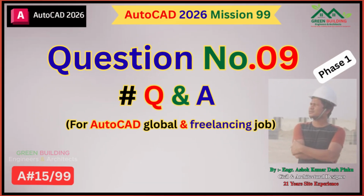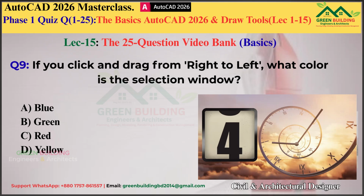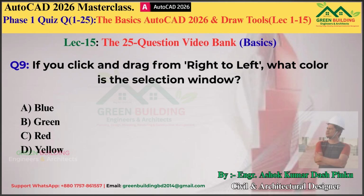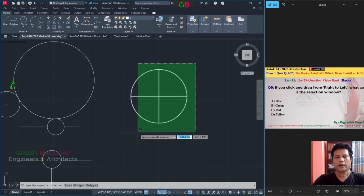Question number 9. If you click and drag from right to left, what color is the selection window? Option A for blue, option B for green, option C for red, option D for yellow. The correct answer is B for green. Let's explain. Right to left, just click here and select. See, this is the green window or crossing window.